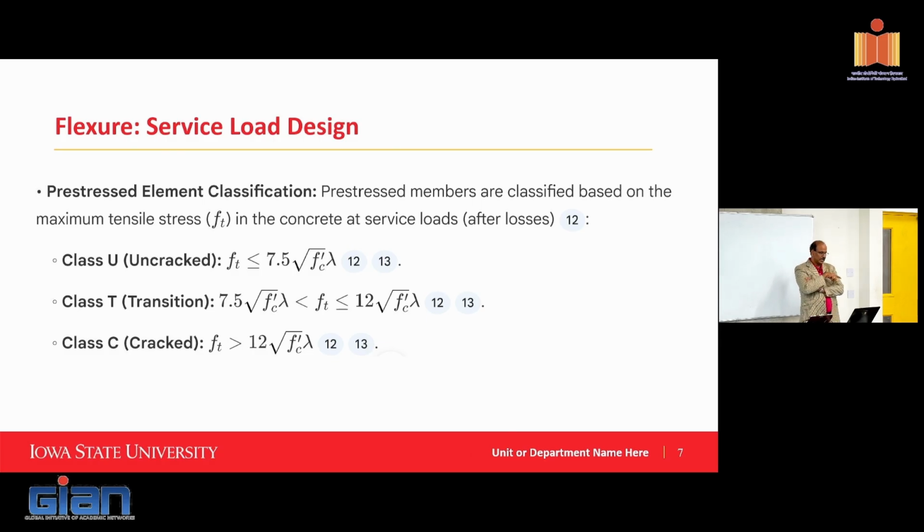So when I say different limit states, your properties should be at the respective limit state as well. And occasionally, if it's ultimate, they take their f'c to be 1.2, 1.3 times what's specified, because precasters do ensure higher concrete strength, and the concrete maturity is also accounted for in that case. So again, it's a comfort level.